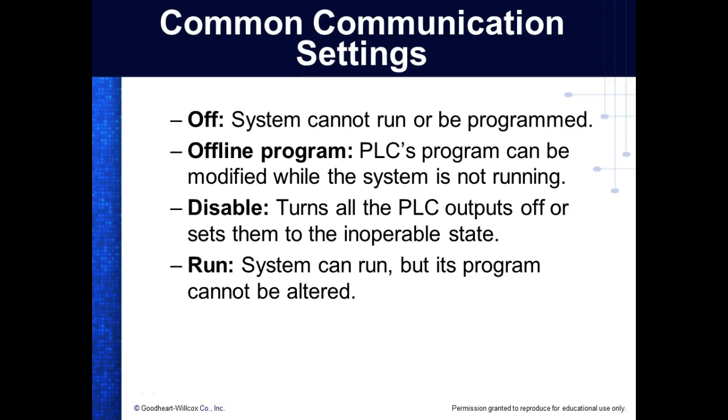So the run mode, when we switch it to the run mode, then the PLC is actually told to run the program, right? Understand that? Everybody okay? Now what Allen Bradley does, when you switch it to the run mode, if you've got your computer hooked up, it'll actually display what we call a monitor that shows you what's going on. This is one of the differences with the Siemens PLC. Once you switch it to the run mode, you have to tell your application to switch the monitor. So it's got a little sight glass thing up there. I'll try to demonstrate some of those just to know the difference.